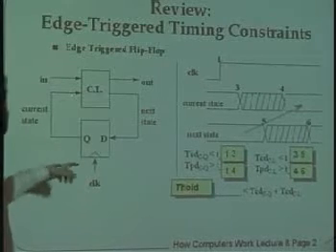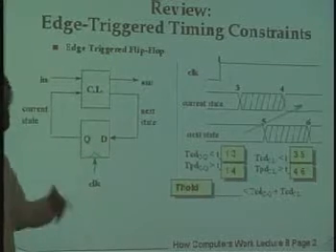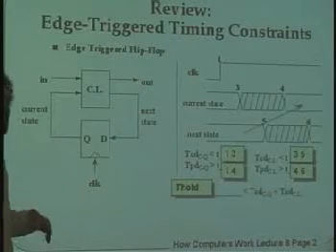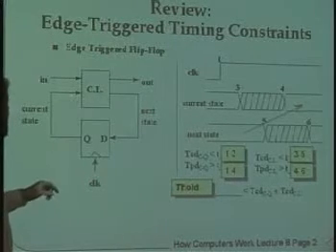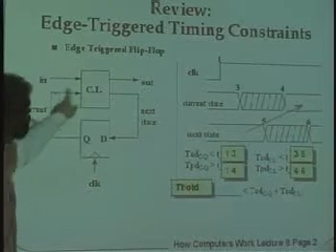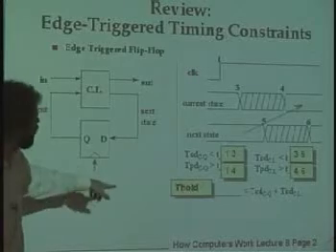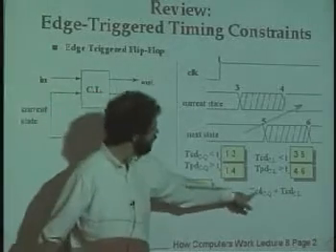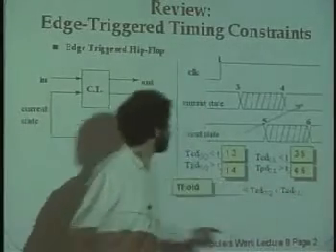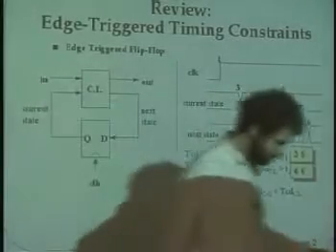In other words, the picture of the data that we're going to take has to stand still when we click the shutter here. And Phil, even before you came, I was talking in these terms. And so this contamination race is basically saying, don't have the contamination race around back to the lens here before the hold time has passed. And what that says is that the hold time has to be less than the sum of the contamination from clock to Q of the register here and the contamination delay of the combinational logic over here, which is how fast we can race around here.